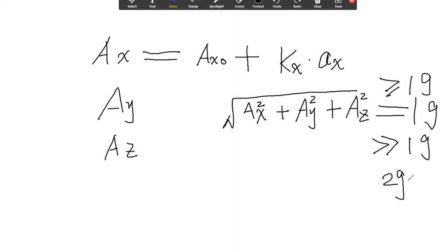So this is one kind of approach based on theoretical analysis. You can do lots of experiments. You can see for different falls what the threshold is. So this is the threshold, maybe you use the threshold as delta AF. So you need to identify the threshold. If you use 1g, it will be too sensitive. That means you frequently have false alarms. It's always telling you that you have a fall, and it's very annoying.